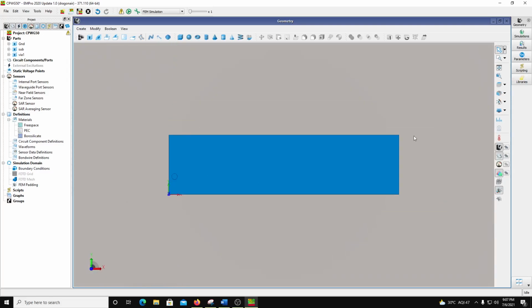Okay, so if I say top view, view all, so that's the story here, and I have to repeat them this way. With a gap of 0.5 I have to repeat them, and then I have to also repeat in this direction. So I have to make an array of it, right? So in this direction, how much do I go? Basically the center is 0.1, 0.5, so 1.15, then again 0.1, 0.25, then 0.3, and then again 0.1.